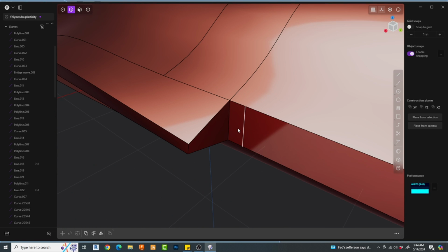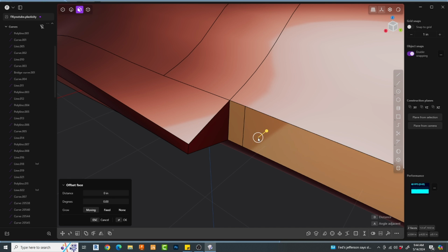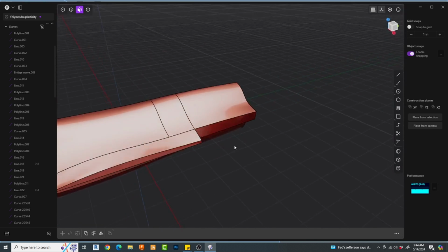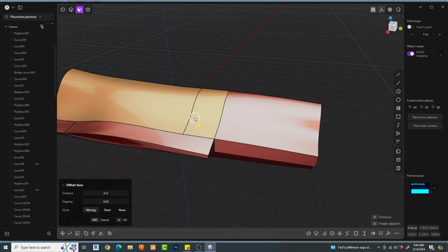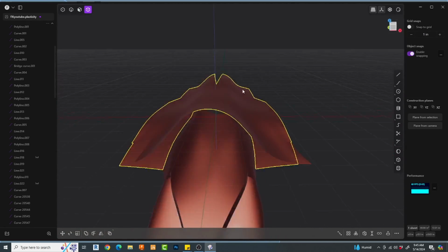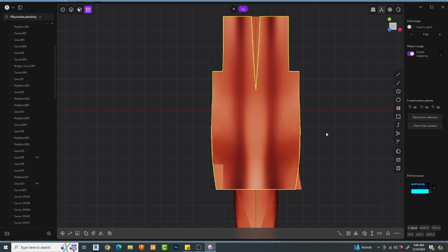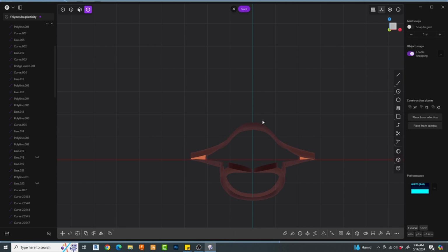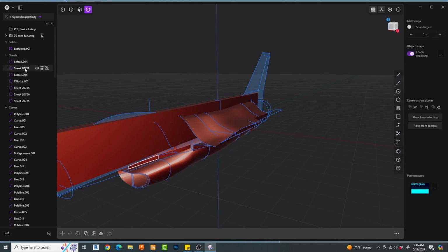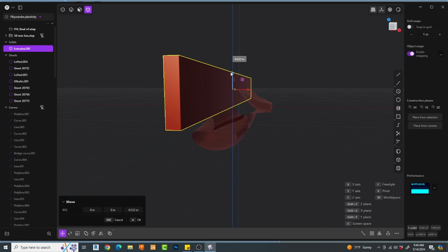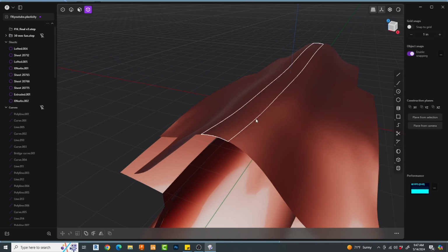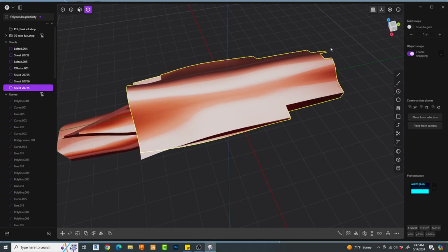Once bodies are joined, I can toggle surface mode here and simply select the both and hit J and clean up geometry. Sometimes this works. I made a mistake somehow here, and I'm seeing the seam on the top, so I'm going to create a cube, and then I'm going to Boolean subtract this from the top of the model. Once I have that done, I'm simply going to do a loft command with proper tangencies.